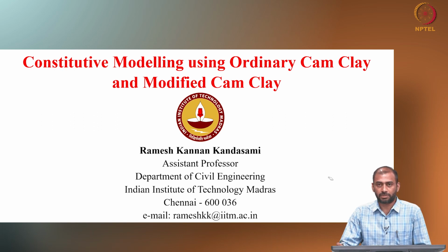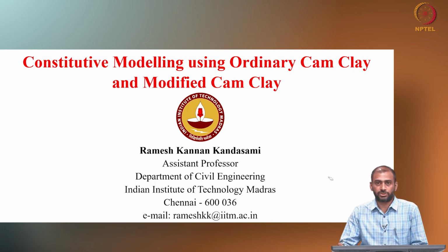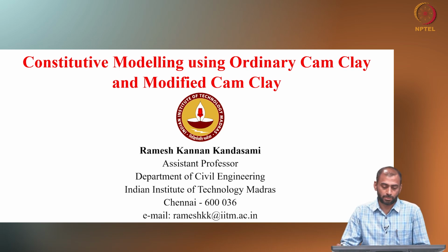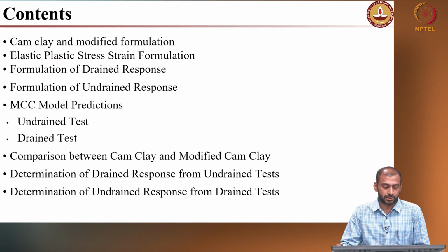We explained the basic tenets of plasticity and how it is useful in constituting the mathematical models, right. In this lecture I will give a detailed description of the Cam-clay and the modified Cam-clay models and their formulation, a brief description of the formulation, and we will also discuss the advantages and limitations of the original Cam-clay and modified Cam-clay models.